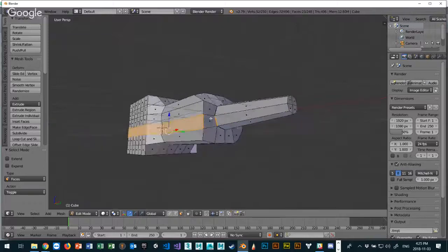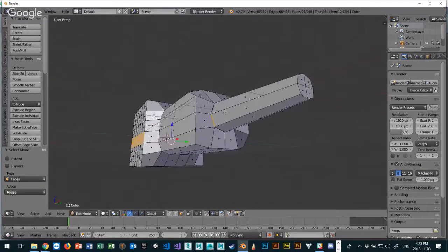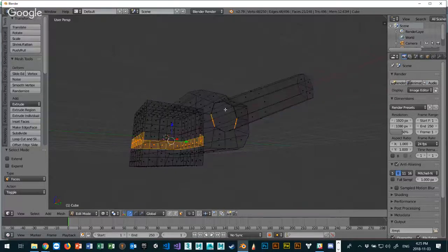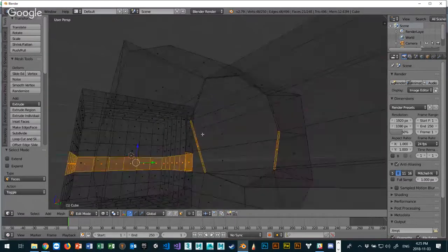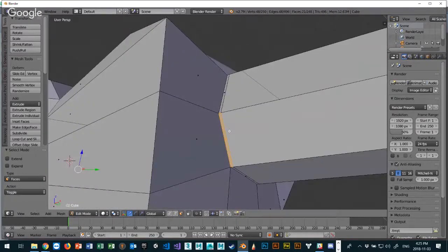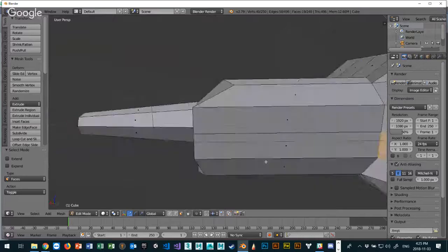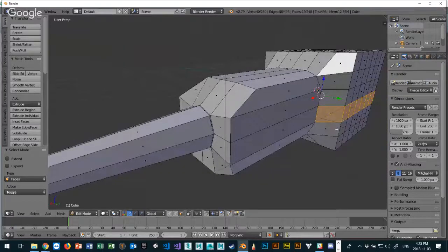But careful, there's some objects that you haven't seen that are inside this. If I go into Z mode, you can see that I've also selected this little face right here that you can't see. There's a small face that I created by accident somehow. And what you want to do is make sure you deselect those faces if you're going to do what I'm going to do. Okay, now what I can do is I can scale it out.